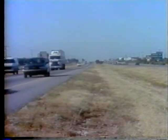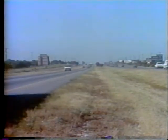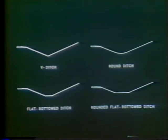The design of a safe ditch is dependent upon the steepness of the front and back slopes of the ditch and, to a lesser degree, the shape of the ditch bottom. If the ditch has a front and back slope of 5 feet horizontally for every foot of drop, a ratio of 5 to 1, any one of the 4 commonly used ditch cross sections is fairly safe.